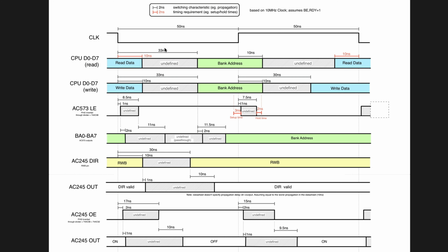But if we change it at the beginning of our clock cycle, then during this whole time, our control logic will be impacted. So there is a bit of a consideration here. We need to control the point in time where our ready input is changed.